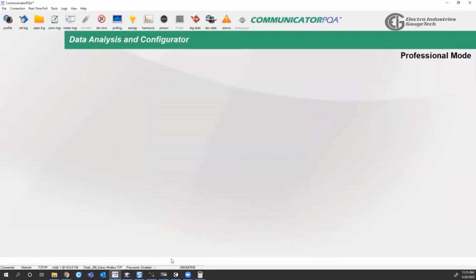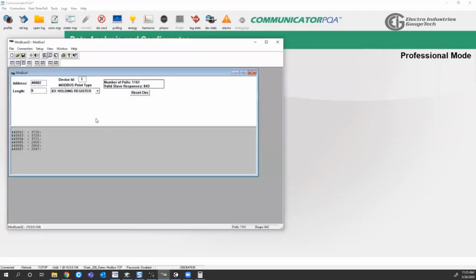So we do offer those three different options: primary 16-bit values that have to have fixed scaling on the meter. We offer the floating point, which will auto scale with the meter. And we also offer the secondary readings that require a scaling or formula to be inputted, but then you can pull 16-bit values while still having auto scaling on the faceplate of the meter. So that pretty much wraps it up for the Modbus polling on the Shark Series meters.